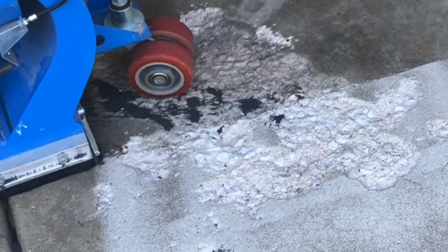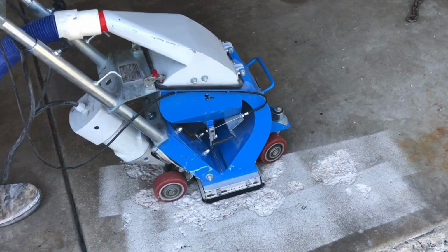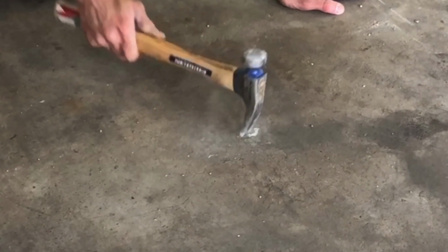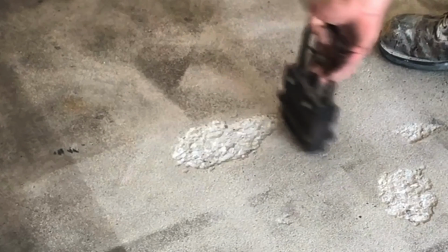With regard to spalling, the spalling is basically going to be any kind of damage that was incurred, maybe nails that were placed in the floor, or any kind of fixtures that were installed to the concrete slab that when it was time to renovate, those pieces or those nails or lag bolts, whatever it be, was yanked out of the slab, and of course the concrete broke away with it, so it leaves a spall. The only other way that a spall would happen other than abuse from fork trucks and things like that could possibly be during placement, where parts of this slab with bleed water and the way that it was placed left hollow spots in the surface of the slab.